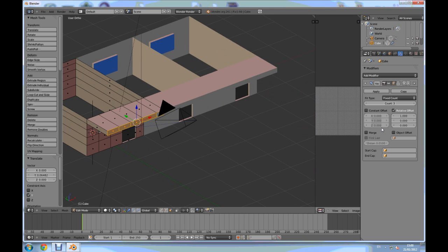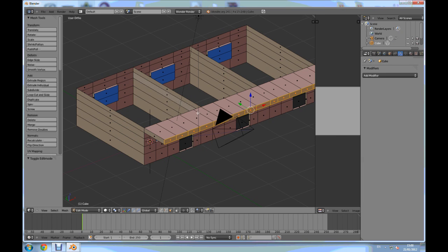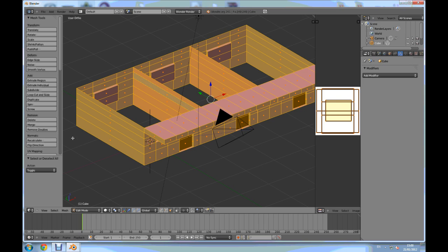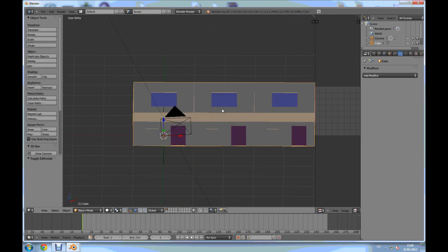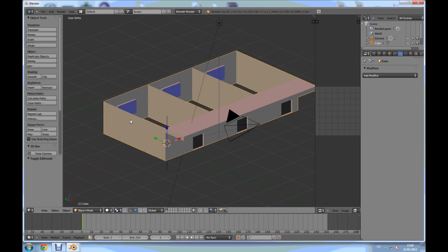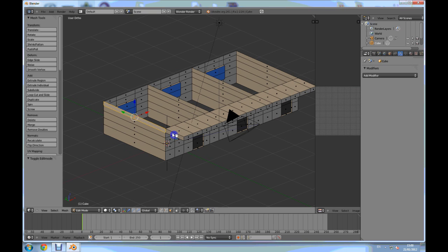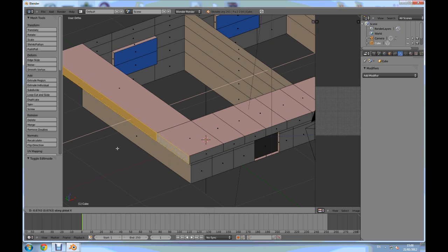Now we can apply, go out of edit mode because you won't be able to apply modifier in edit mode. So object mode, apply, tap, A to deselect, A to select all, remove doubles. We've got some overlapping faces here. Now they are gone. So now this is brilliant. Yeah. Few adjustments. Go to edit mode, select 1, 2, press E to extrude X, and extrude about 1.2.